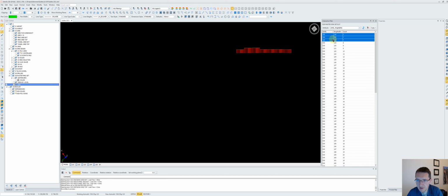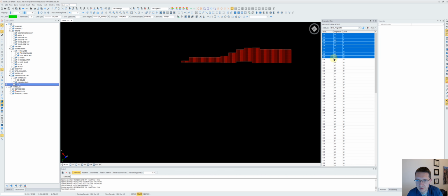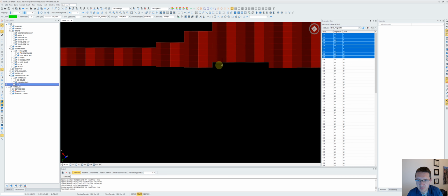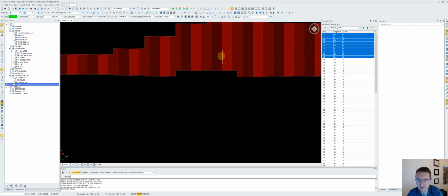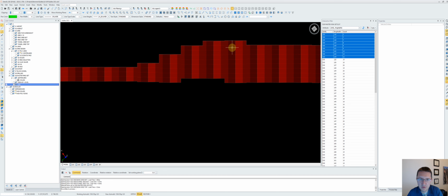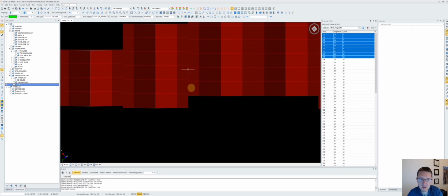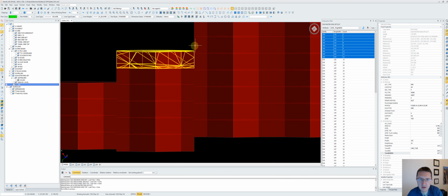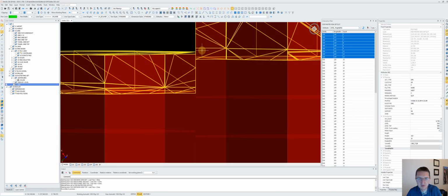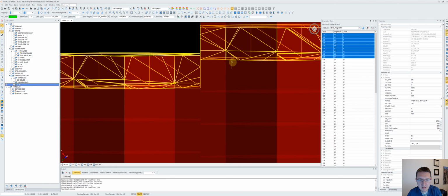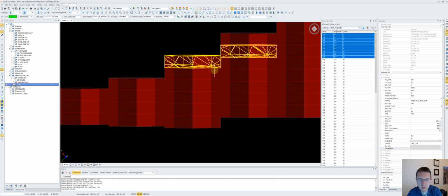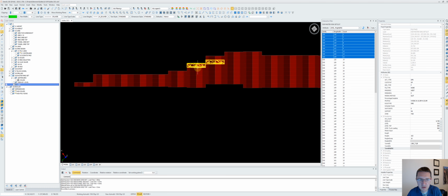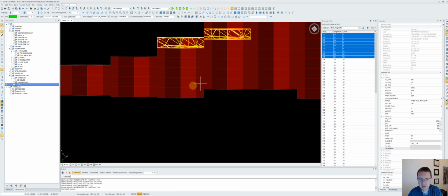Make sure there's something here that you're probably going to want to fix. Right here. You see that? These rings didn't get assigned those values. And what this could be a cause of is, see how these aren't lining up perfectly? These two right here, there should be a nice straight line lining those two up. And to do that, you're just going to have to make sure the center lines are lined up. For this, I don't really care.